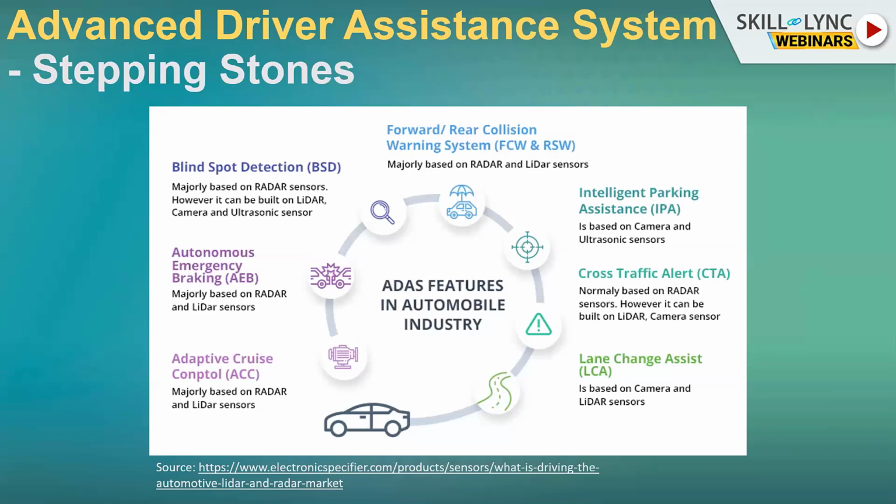In case the car in front of us is breaking down, this system is intelligent enough to guess that the car in front of me is breaking down, and it will try to adapt its speed. Even though we've set a speed of 120, if the car in front of us suddenly slows down to 100 kilometers per hour, our car can sense this and adapt our speed and slow down to 100. And it will always try to keep a safe distance of 2 seconds or 3 seconds, based on the requirements, to keep following the lead car.